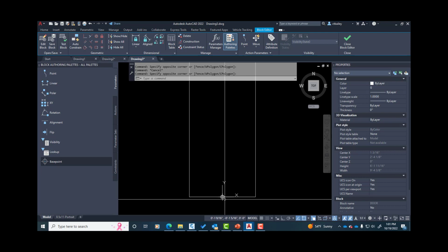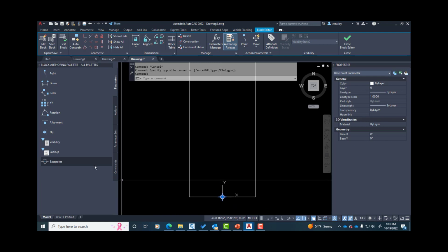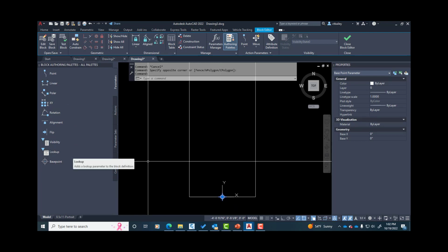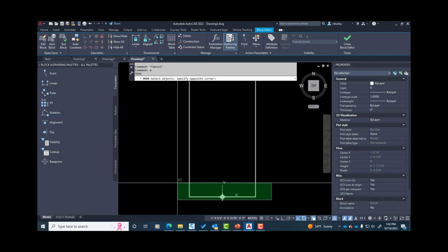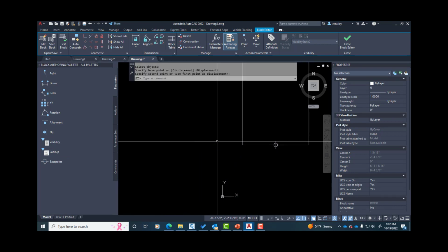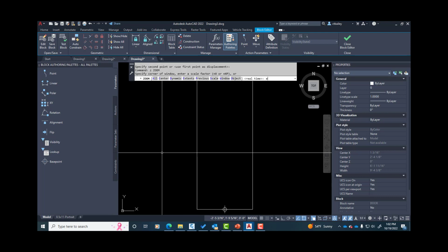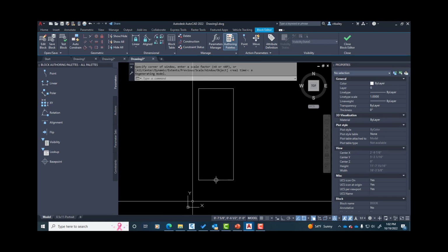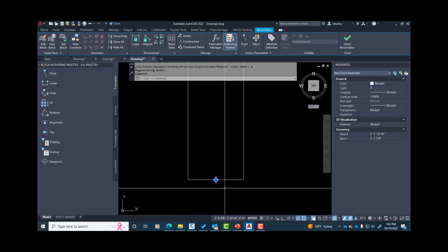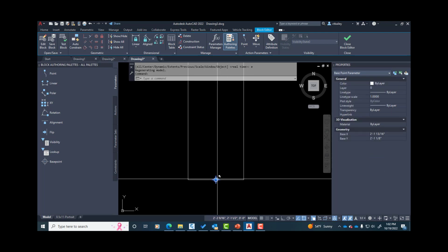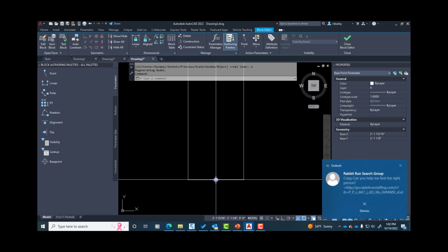When we have the base point parameter brought in, you can actually move the polyline and the base point over to here. And so if you do a zoom extents, we have the icon down in the lower left, but the little base point is going to become the insertion point of the block, even though it's at coordinates 2, 2, something or other.